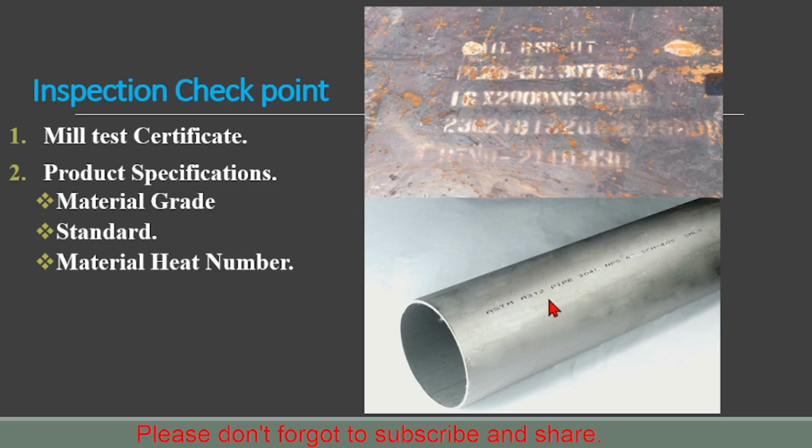So for the material grade, the writing here says A312 pipe 304L. So this is an SS pipe. Here the writing has the material grade. Then we can see here the material standard. So this is the ASTM standard. We can see the specification also, NPS 6 inches, schedule 40. So we can find the heat number also like that. So here there is one heat number.